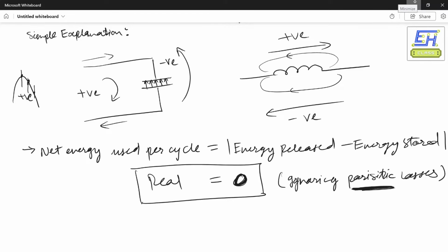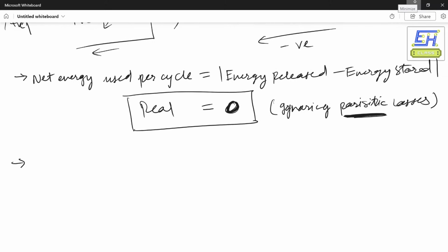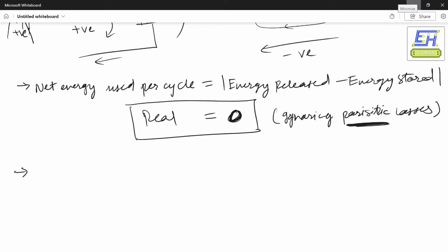So what this means is that this current that flows instantaneously actually takes up the capacity of the transmission line. Even though it's momentary, this reactive current associated with the reactive power is taking up the capacity of the transmission line, oscillating back and forth.